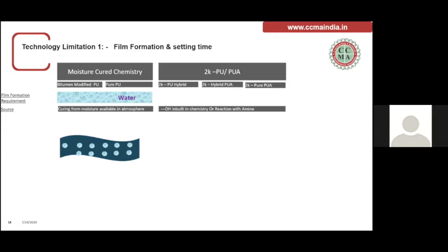The limitation is the relative humidity, the humidity in the air. At less than 85%, from 50 to 80, it gives a fantastic film. In most Indian conditions, it is not a problem.